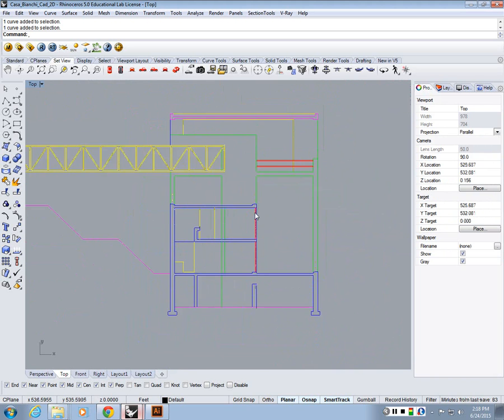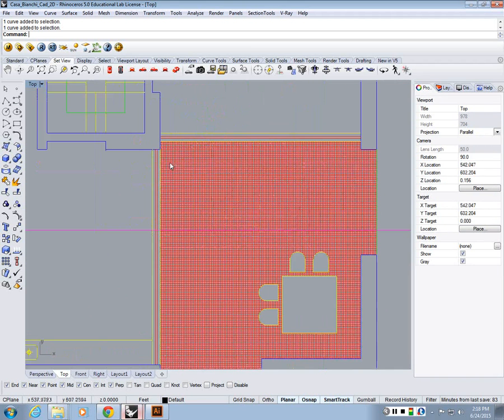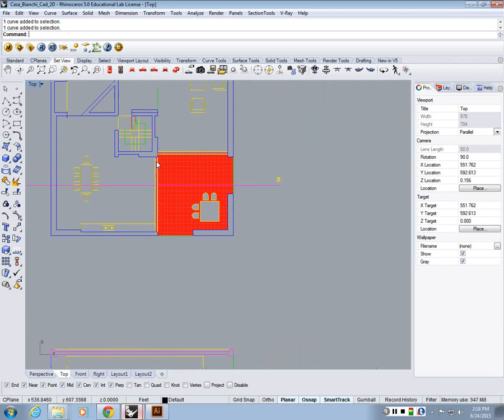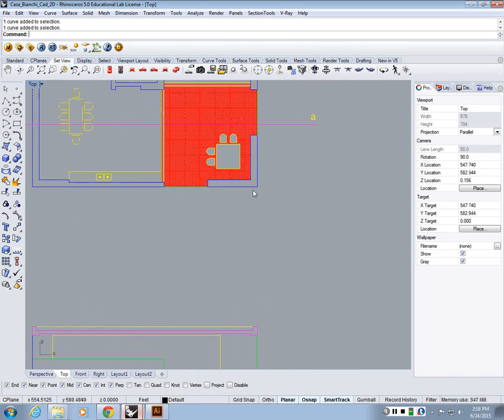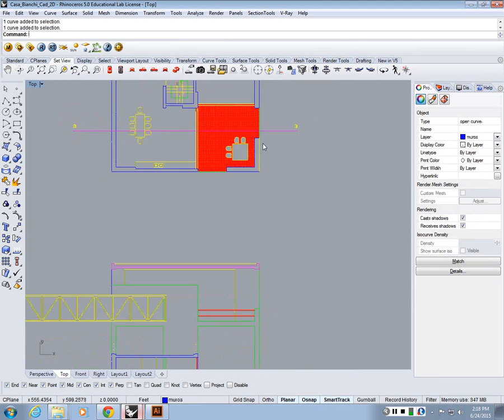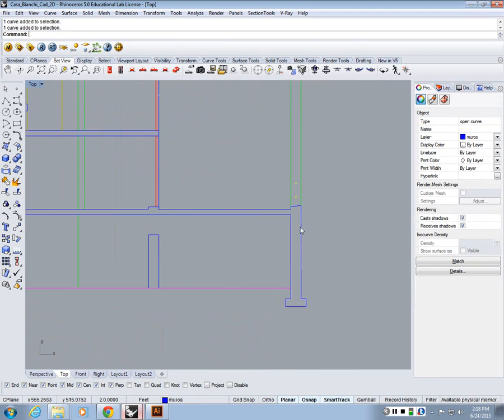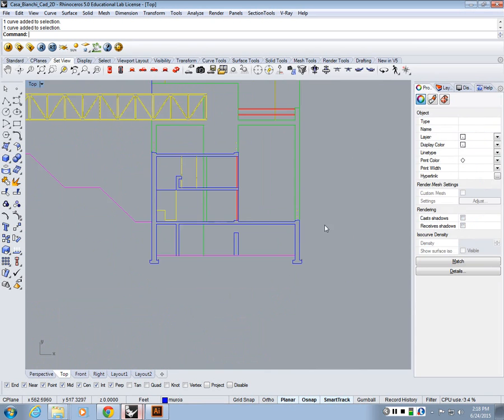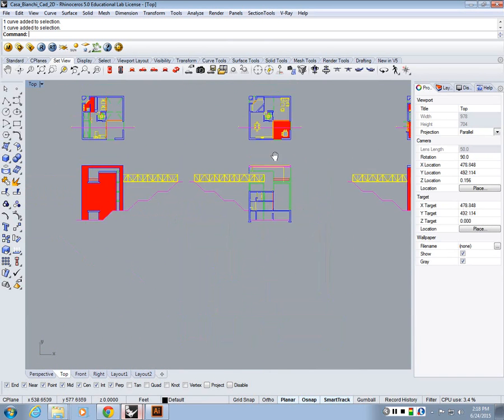And the windows are the same as in the plan. Because technically, when we are cutting through something, even if we are cutting on the plan or in a section view, we are basically seeing the same material in a different orientation, right? So it should be on the same layer. So when we give them a line weight, whatever the line weight is on the plan for the walls should be the same in section when we are cutting through them. And same thing goes for elevation.